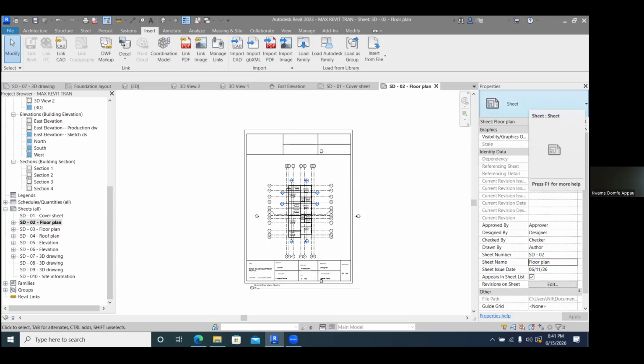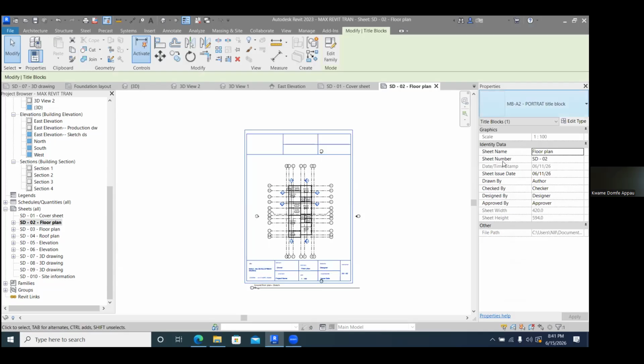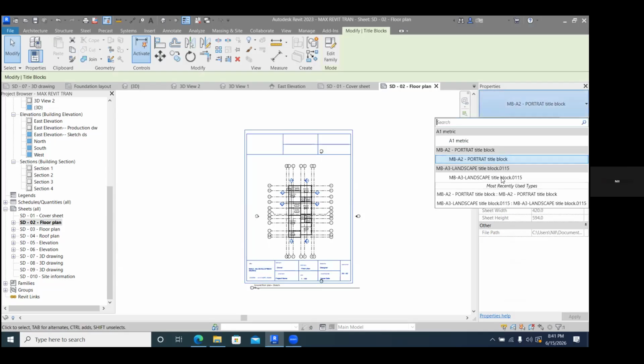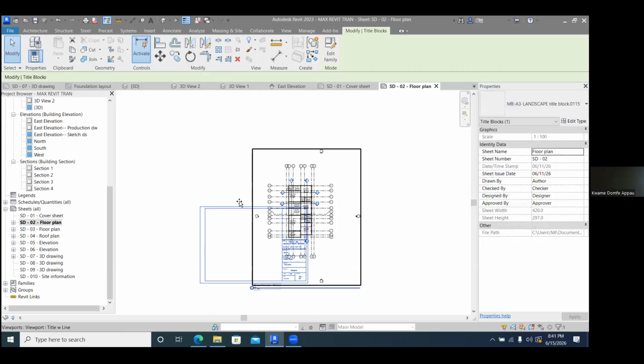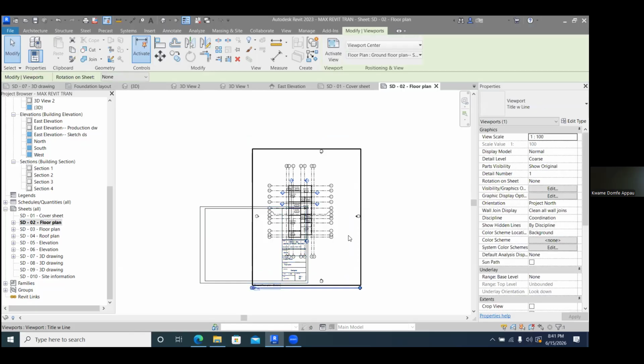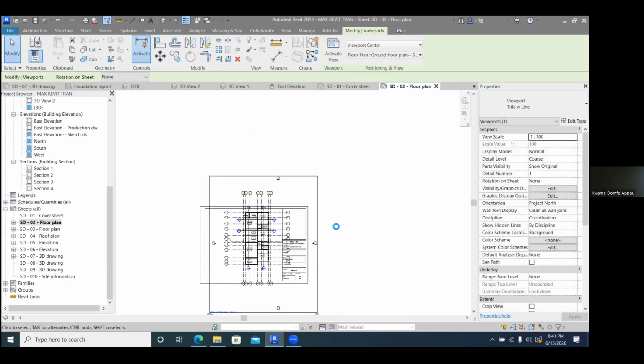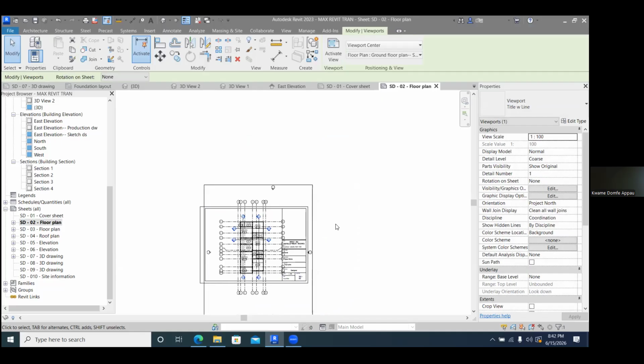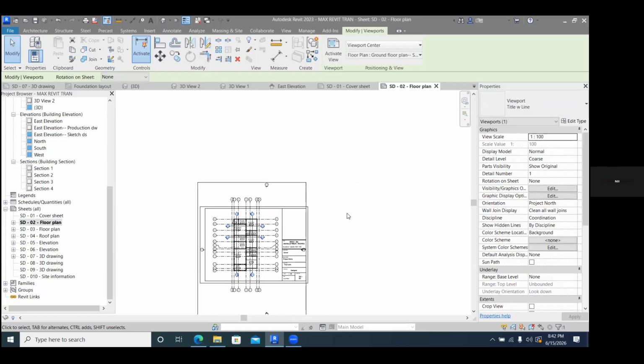You have to select the title block first. Yeah, so that's the sheet. You have to select the title block before you can change it. Okay, sir. So I should go to A3. Yes, go to the A3 one. Set the A3. Yes. Now put the view on it well. Don't move the title block, move the view around and position it well. But you see the view, center the building well. Let the building go to the left small too. You see the building can easily fit. It's the green lines that we need to make some adjustments.